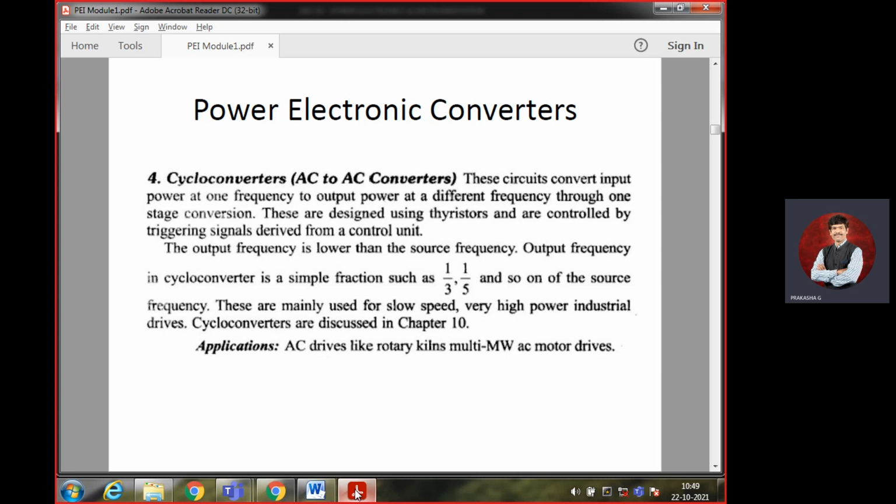Now I will put the regulator to 0.2. When you put the regulator to 0.2, instead of 10 kilo ohm, it reduces to 5 kilo ohm, meaning the resistance is reduced further. Since the resistance is reduced, the current flow increases. It's inversely proportional. As the resistance increases, current flow decreases; as the resistance decreases, current flow increases. When I put it at the final stage, maybe I may have around 500 ohm. Just assume, I don't know what exactly is there.